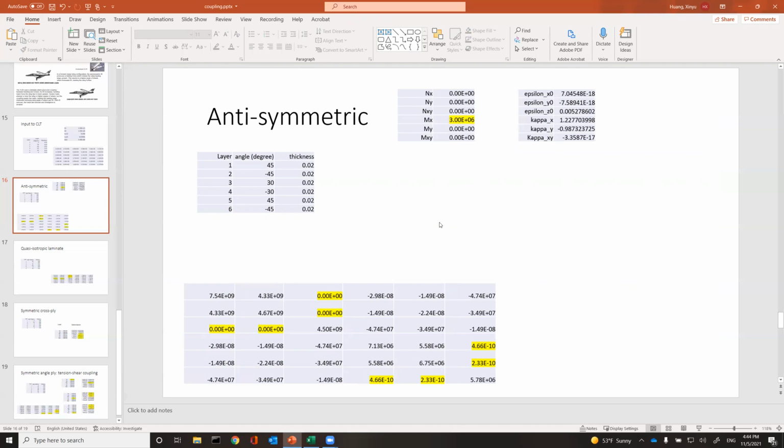I did nothing but bend it. I actually have shear. You see this in-plane deformation? This is strange. This is due to a coupling effect because my B matrix is not 0 now. So I have some big terms, really big terms. That produced the bending shear coupling, in-plane shear, in-plane deformation. So my out-of-plane bending produced in-plane shear. Now these first two terms are essentially 0.